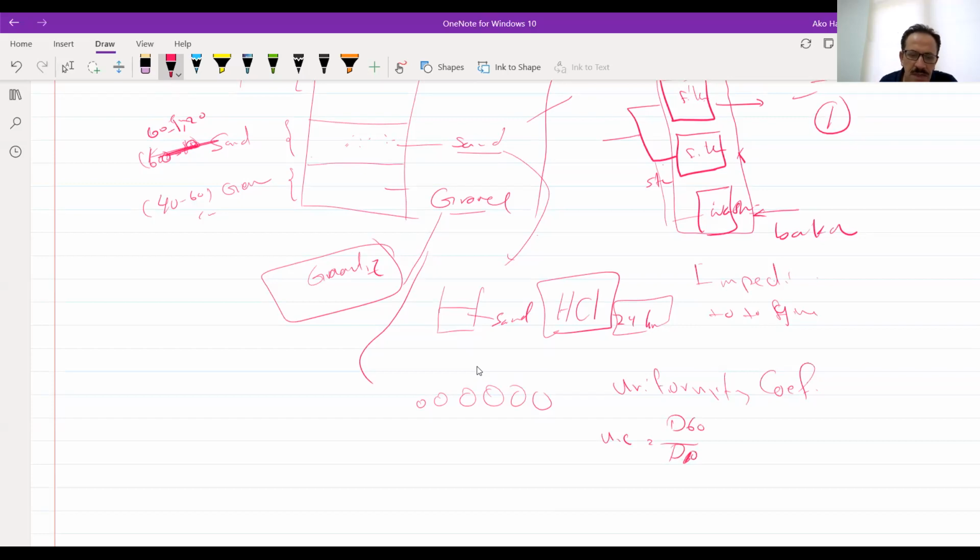When you draw the sieve analysis, there will be the scale from 0 to 100, the diameters of the gravel, and the percentage passing, or finer than the stated size.